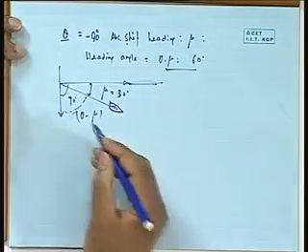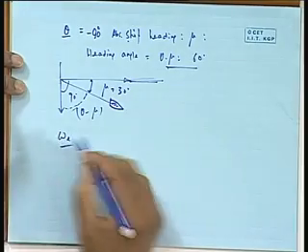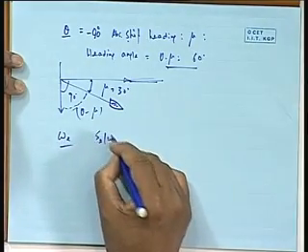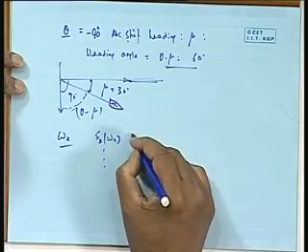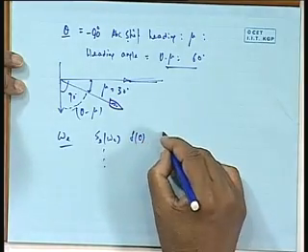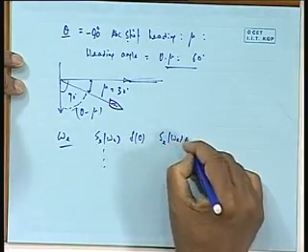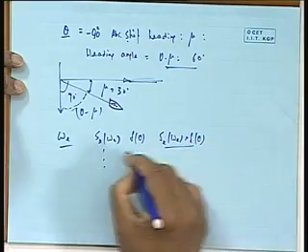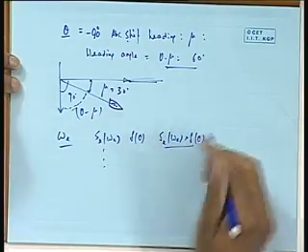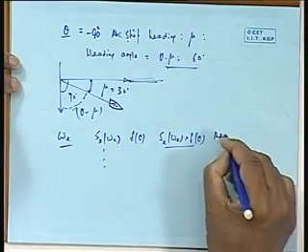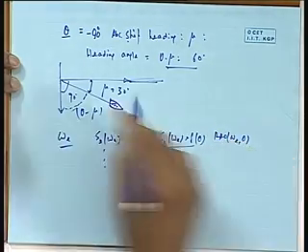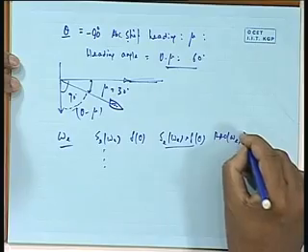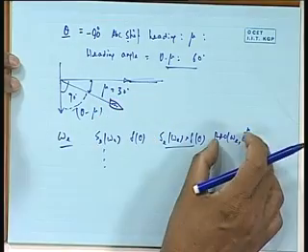So for this, now I will figure out S_ζ(ωE), which I have got, in fact there has to be f(θ). So therefore I have S_ζ(ωE) into f(θ). That becomes my component for the 3D part. Here I have got RAO(ωE, θ). Remember, theta actually is not theta, this is theta minus mu. This is theta minus mu, that particular heading. That is that RAO.